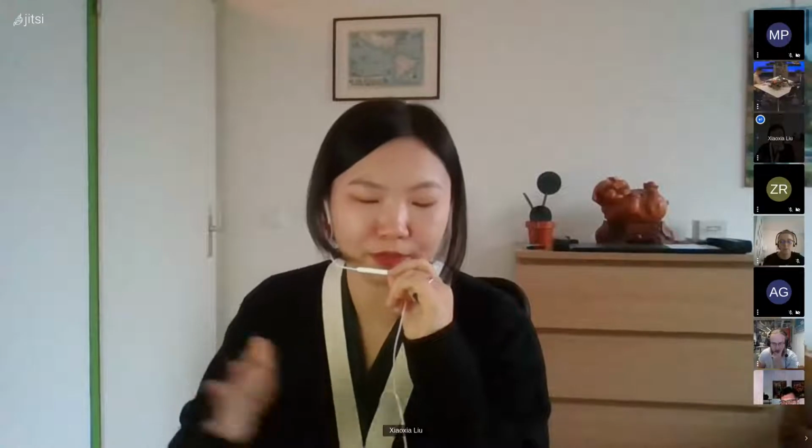Hi, thank you very much for the question. Actually, the scaling problem for drinking water really depends on the calcium concentration of the local drinking water, which varies a lot at different places. And as Michelle already showed, for some drinking water systems there's also temperature fluctuation, and the solubility of calcium carbonate decreases when the temperature goes up. So for a very long time, the scaling problem has always been seen as a problem from the increase of temperature. So it has never been associated with any microbial activities in the system.